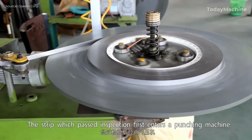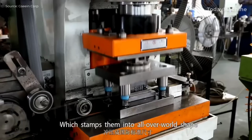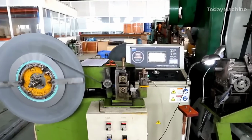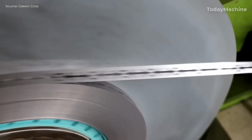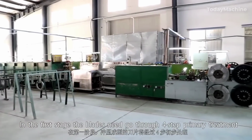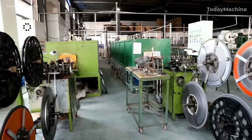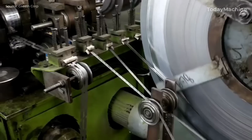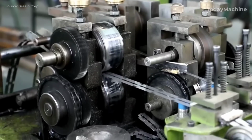The manufacturing process of razor blades begins with stainless steel strips, which are first inspected for quality. Once approved, the steel strip enters a punching machine that stamps it into the desired razor blade shape. In the first stage of blade treatment, the blades undergo a four-step primary process. The first step is heating the blades in a furnace at temperatures exceeding 1000 degrees Celsius. This high-temperature treatment alters the blade's molecular structure, preparing it for the subsequent steps.